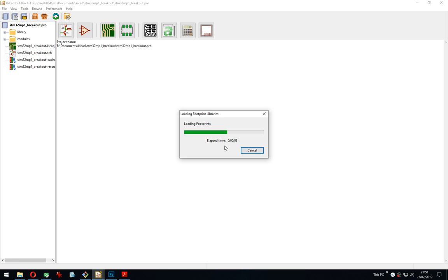Okay, so I claim the PMIC symbol done. Now I think I will go for creating the BGA footprint, which hopefully should be fast with the generator. After looking quickly, it seems the PMIC footprint is also missing because it's kind of unique, but the QFN generator, I believe, should also help with that. Look how long this is taking, just loading all the footprints. It's gonna be like 2 minutes.